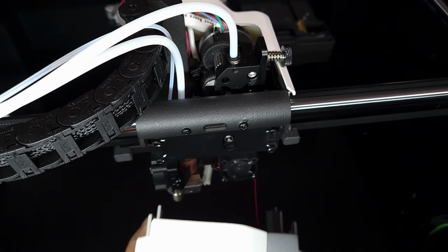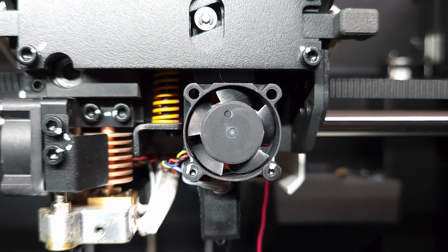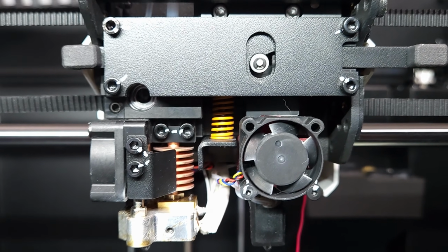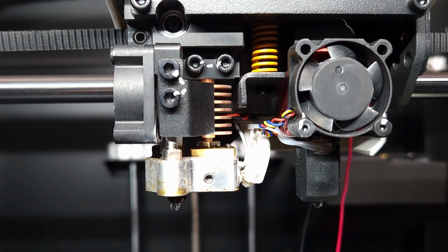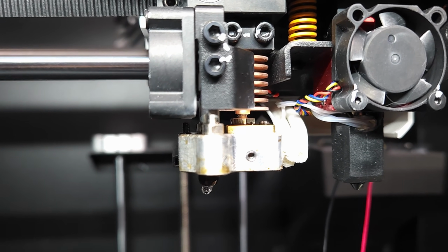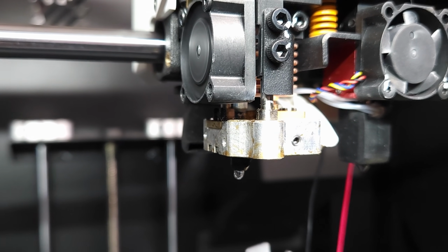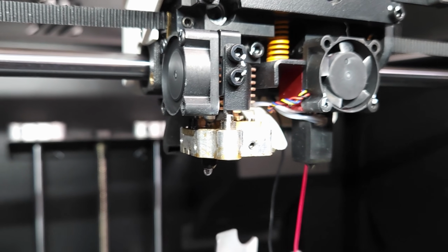Moving to the print head and taking the cover off, we can get a closer look at how this mechanism works. The right-hand nozzle is lifted and lowered using a mechanism that's actuated when the head moves to the left and right and runs into its end stops. The left-hand nozzle is the co-extrusion nozzle. The carbon fiber goes straight down through the top, and then the filament comes in from the side through a couple of right angles and then out the nozzle.